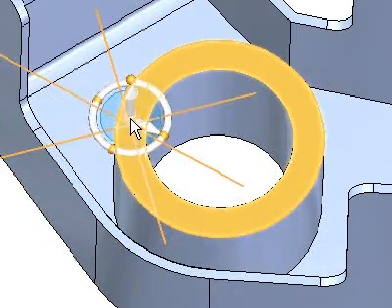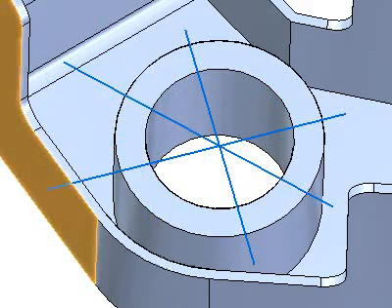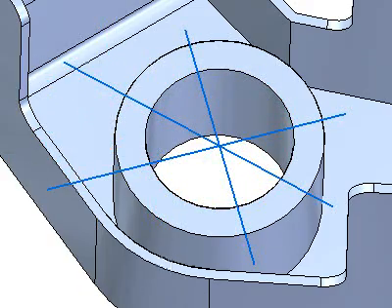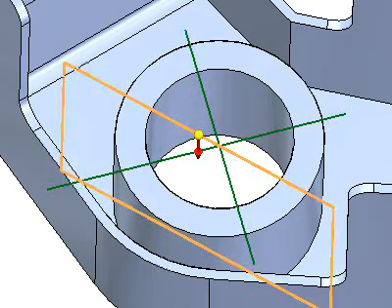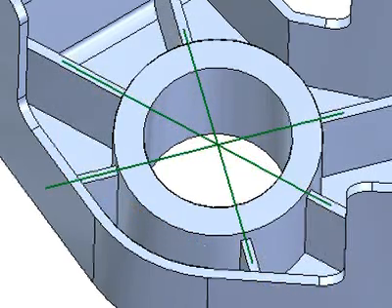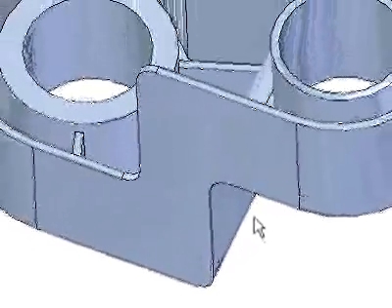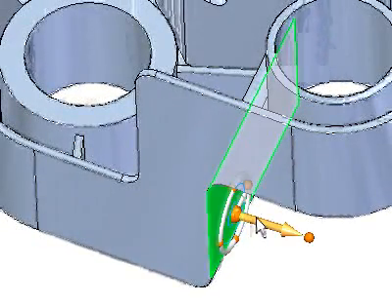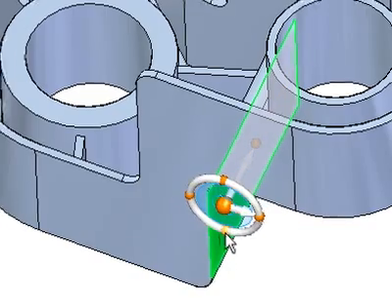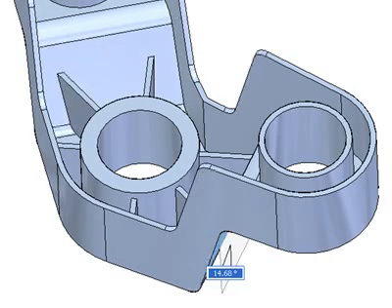We'll add some stiffening ribs, starting with a sketch retrieved from a library. Because thin-wall operations in Solid Edge are procedural, users have full edit control without model regeneration. As we taper the vertical face, notice how wall thicknesses and symmetry are preserved. These edits happen without regenerating the entire model, but in a history-based system, this simple change would force a costly rebuild on the entire shell and rib operations.